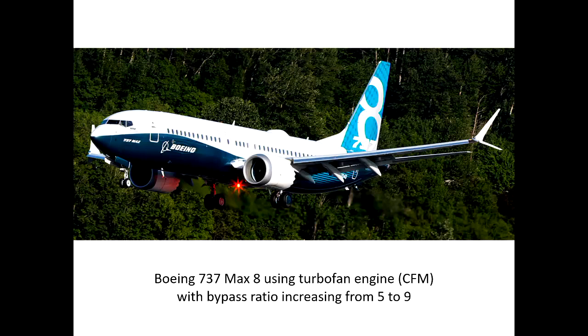In that case, during the test flight, the company noticed a problem. So they implemented software to automatically correct that trend. During the flight, if it detects that the nose is too high, the software automatically kicks in and tries to tilt the nose down.